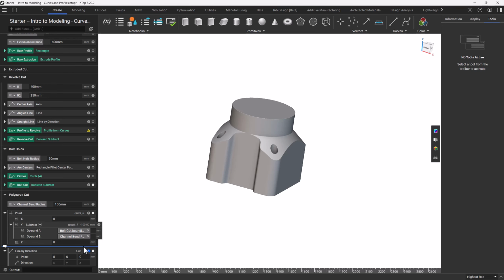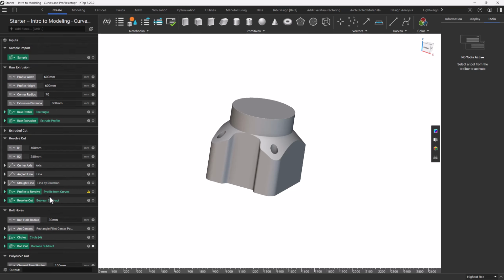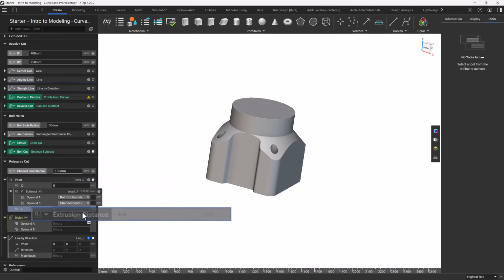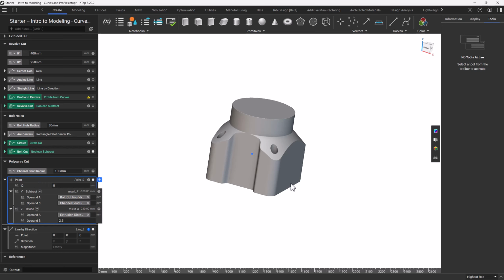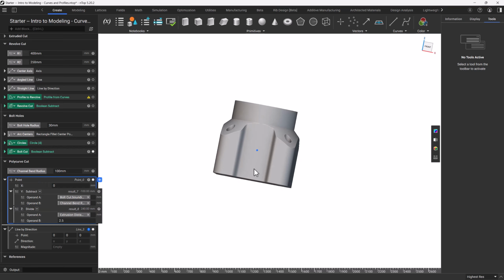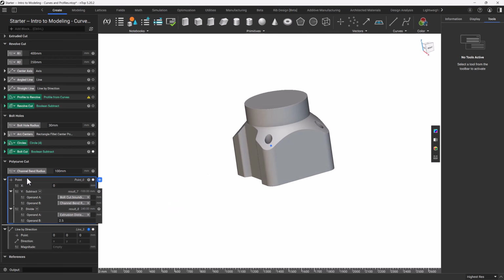To automatically give us that value though, I can load in a divide block. And if I divide our extrusion distance from the top by 2.5, this will give us the value we're looking for our Z. If I click on this point, I can see it's about halfway through this solid region here, and it's correctly situated on both our X and Y axes.